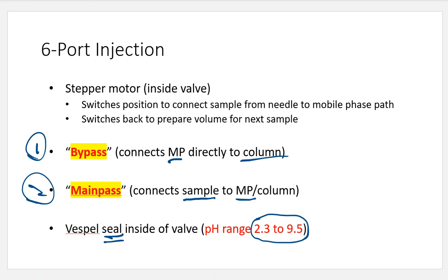So this means again, on top of the LC system, I should not have a bottle of straight up hydrochloric acid. On the HPLC system, I should not have a bottle of straight up NaOH solution. Chances are those pH values are going to be lower than 2 and higher than 9.